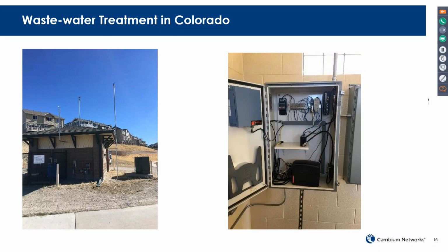You see that this cnReach radio is mounted on a beam rail in the enclosure, and then you just pull a cable to the cnReach and all the way up to the rooftop. Use a Yagi antenna, and you're good to go.